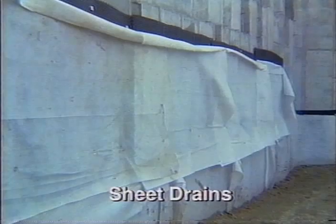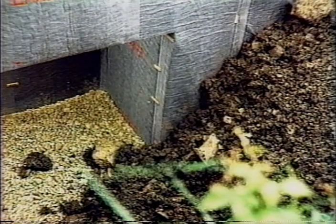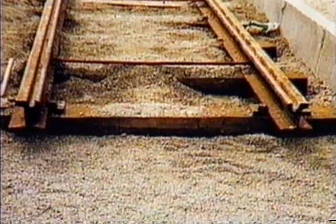Sheet drains, placed behind abutments or retaining walls, are an integral and critical part of the wall system and must be designed to last the life of the structure. The drainage composite must accept a calculated seepage flow from the backfill, while the geotextile must provide adequate filtration without clogging or causing piping in the soil. Here we see a drainage layer placed between the ballast and subbase below a rail track. It collects and drains water from the underlying subgrade and the ballast above.